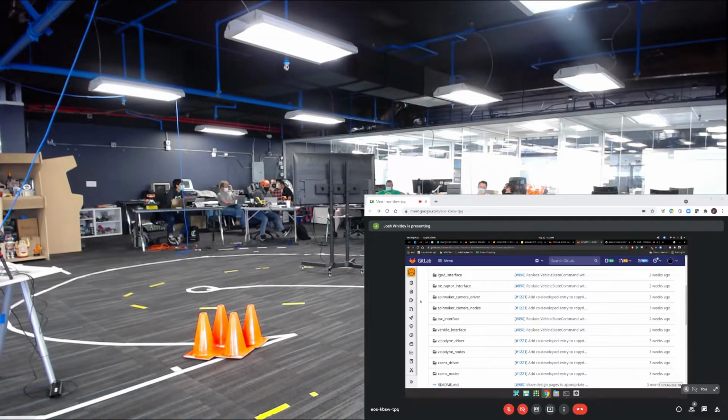So yes, if you release a ROS package to the ROS build farm, nobody at OSRF or anything like that checks your code to make sure that it's not malicious. It is based on a trust system, and that's just the way they've designed it. So if you want to guarantee that any code that you use in your autonomous system is safe and will not do anything unexpected or malicious, you better look at every single line of code that you're including.